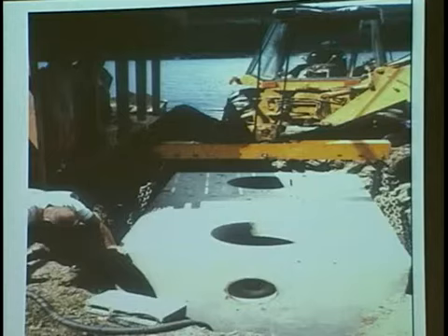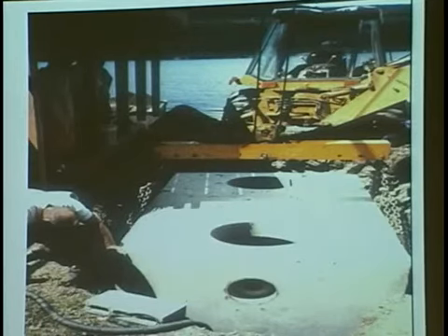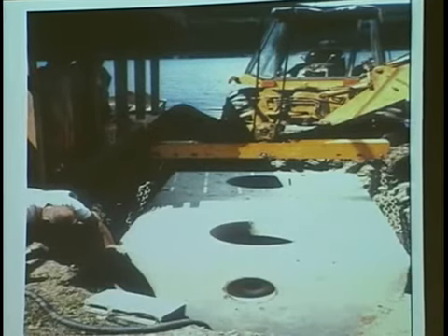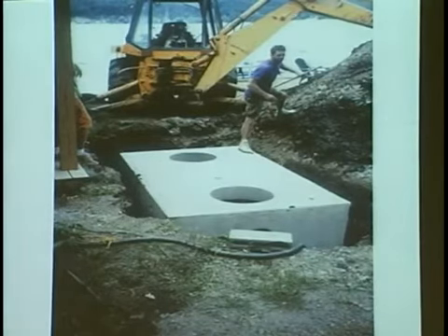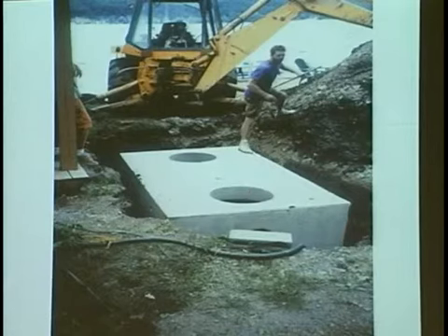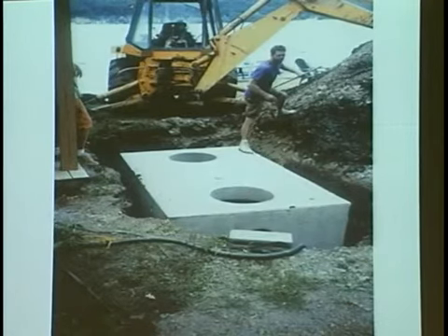So we do allow holding tanks as a retrofit repair once it's been demonstrated by a licensed design professional that no other system is going to work. The homeowner is required to have a high-level alarm on it, with the alarm set with 1 day's capacity left before they need the pumper, and then they are to send me a copy of their pump-out receipts. That's one method of trying to keep track of them to make sure that they are being pumped out when they need to be. There's that coarse fractured shale. That's all there is out there around that lake. Now look how thick this slab is. It's a live load slab on this tank.